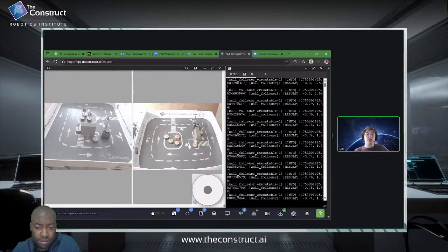Yes, absolutely. That's what I was saying. The service server gets called to move it to 0.3 away from the wall. If the robot's starting position is not such that the front is directly perpendicular to the wall, but rather it's facing towards the wall slightly, this can lead to a condition where it mistakenly detects a corner at a certain distance. It's like, oh, there's a corner here. The logic says I need to turn.